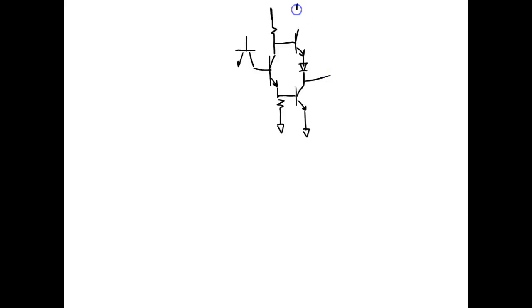And this is this right here. We have a resistor right here. These all connect together, and I can't put the power up there. And normally we put a diode right here to prevent us from putting a negative input on the gate. So it would clip a negative input off. So this guy in the front is just for protection. So it does nothing. This is a TTL inverter.